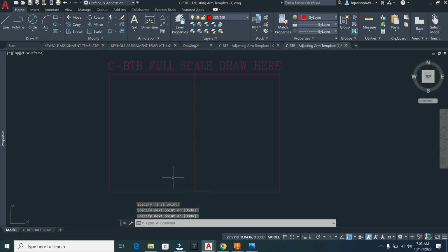And then I'm going to draw another line, about 3/4 of the way up. I'm going to make sure my ortho mode is on down here. And L, space, and I can draw, I'll do it a little bit lower than that, probably right about here. I'm just splitting this line in half, same as we did for our last drawing. Draw it all the way across like that.